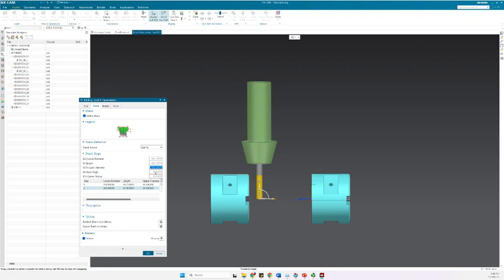That would be either this one, or you can even give it a taper angle, for example. Otherwise, there should be a problem here. I think it's this one. For example, something like that, taper angle 20, upper one. Oh, okay, this is defined. So either you need to define this or this. So 20 I put for the diameter, then the length 50. What will happen if I put this one 20, for example, something like that.